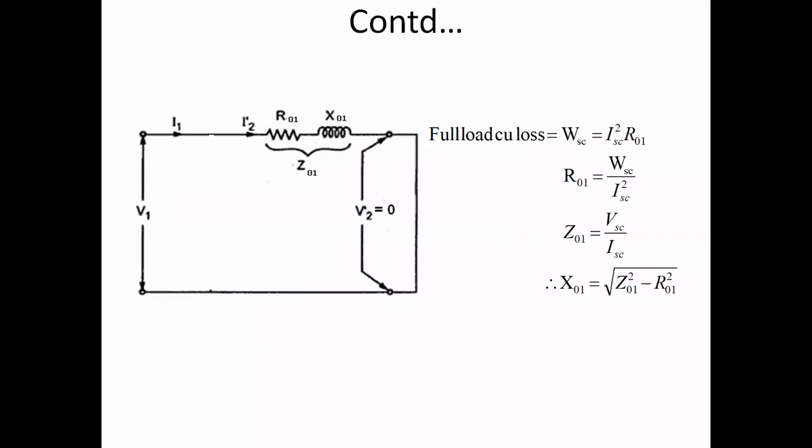See here, during the short circuit test, the short circuit power input is this. Then we calculate R01, then Z01, then X01. This is very important, my dear. From the short circuit test data, this is used in your numerical.